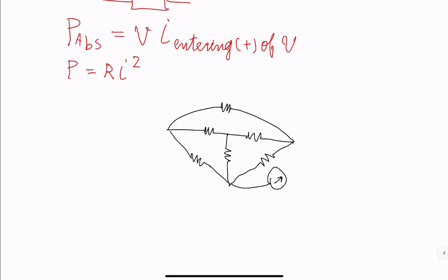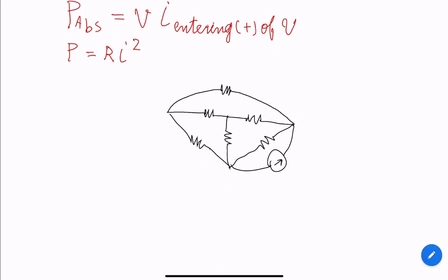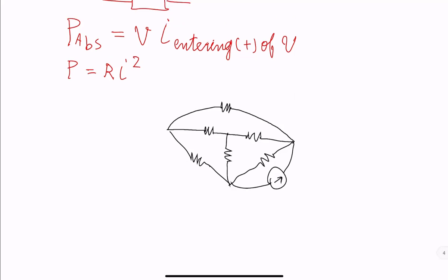In other words, if we look at the same circuit, and this time we take, let's say, the node on the top right to be the reference node, then we are saying here we have 0 volts. Solving the same problem, we find the voltage of that node to be -2, voltage of this node to be -1, and voltage of the bottom node to be -3 volts.